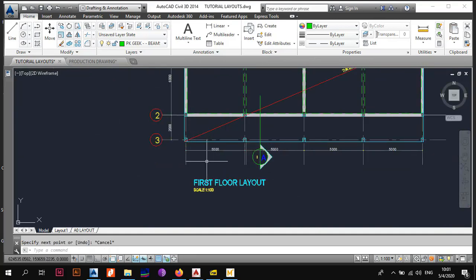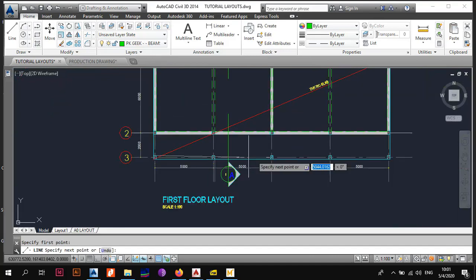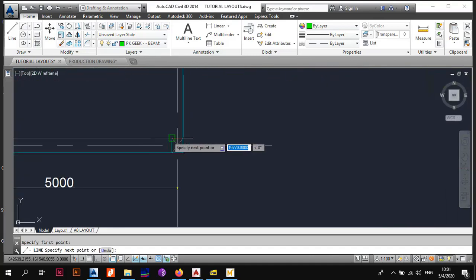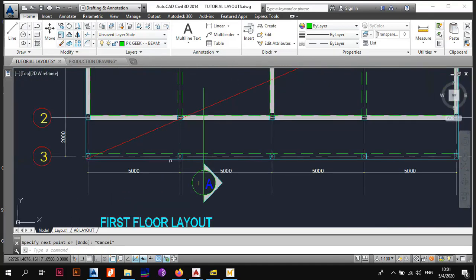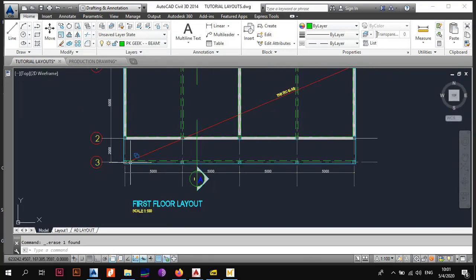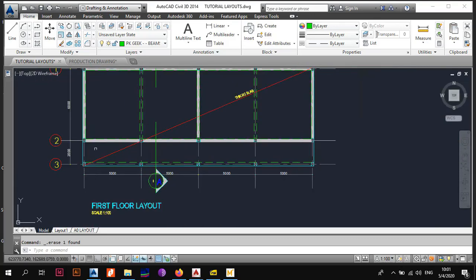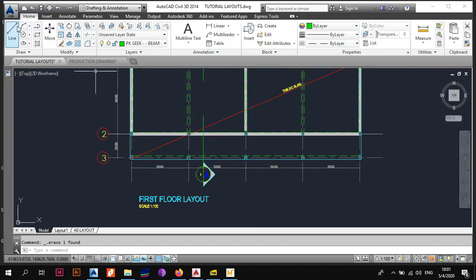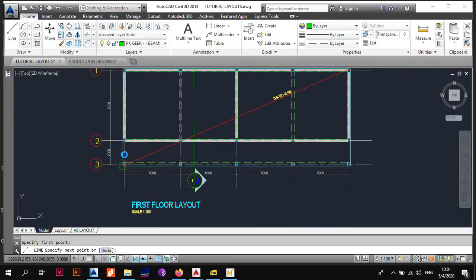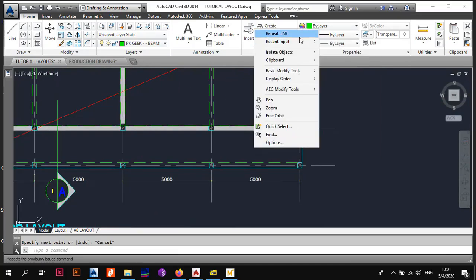We want to create a beam. So yes, we have the beams layer selected, so just create another huge beam. It's going to be a continuous beam supported at the columns, as you can see. So we're going to have a continuous beam for the balcony, which will be joining the columns, and this will also help in providing the bracing for the building. So remember, whenever you're doing your buildings, you want to provide the ties, so this will provide the ties.